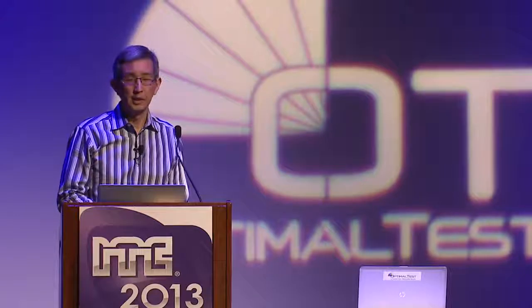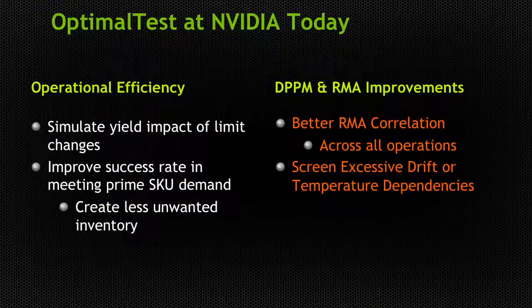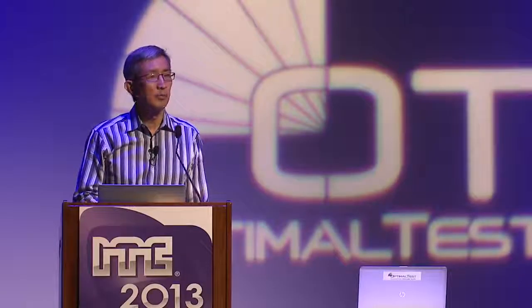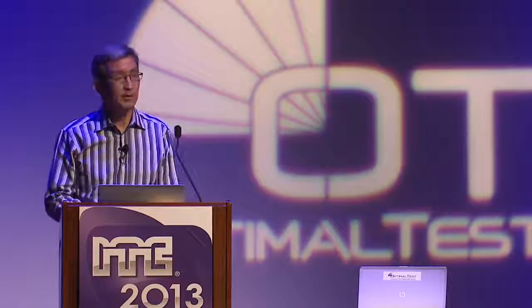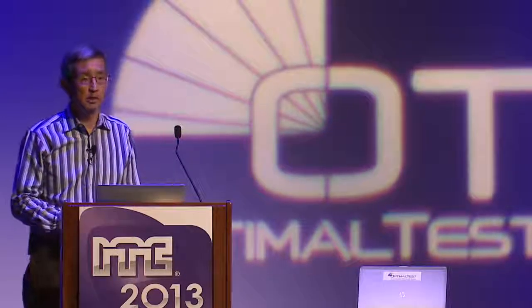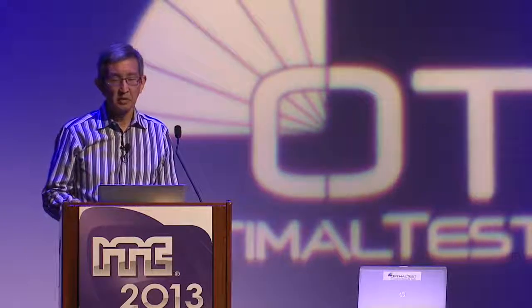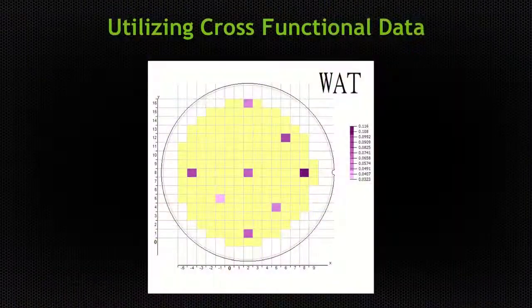We're also using OT to improve our customer quality. By putting RMA data into the same database, we can correlate customer failures to any combination of parameters at any combination of test steps or test operations. The other area we're leveraging OptimalTest is to help us test for drift. So we now have an easy way to screen out a part if one of its parameters changes too much based on different temperature conditions or something like a burn-in stress.